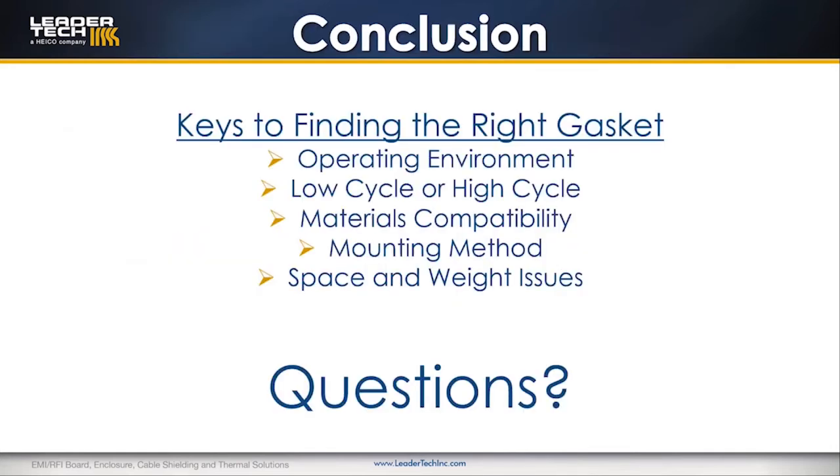In conclusion, here are some key points to ponder when trying to determine the best enclosure shielding gasket for your application. What is the operating environment? Is it inside or outside? Is it a high cycle or a low cycle application? What materials will the gasket be mating to? How do you require the gasket to mount to your application? Are there space and weight limitations to your application?